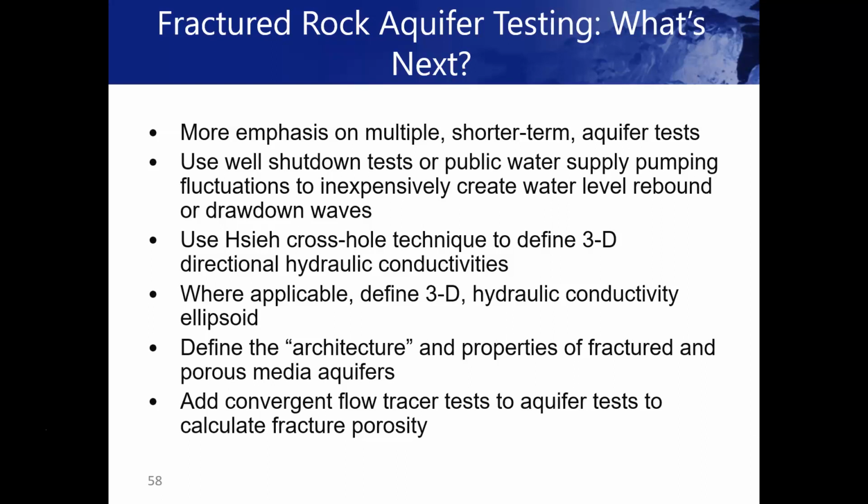But I think where we're heading, maybe I can speculate. I think we should put more emphasis on more shorter term aquifer tests, particularly in fractured rock. There's no reason to do long-term tests unless you're trying to build a water supply well or something. If your objective is measuring hydraulic conductivity and specific storage and understanding the three-dimensional extent of the aquifer, you can do these short-term aquifer tests quickly and inexpensively and get a lot of good data nowadays.